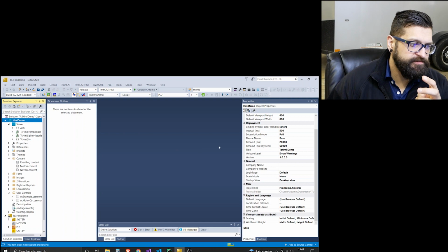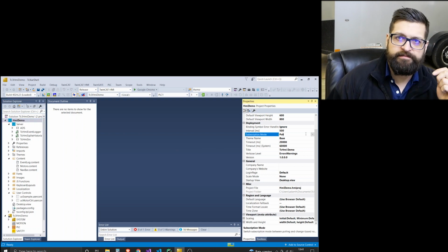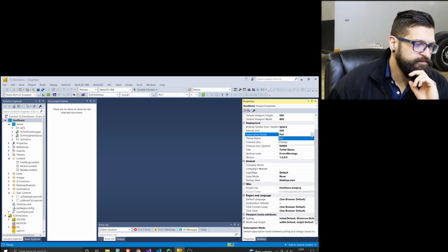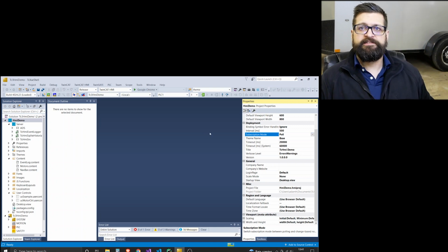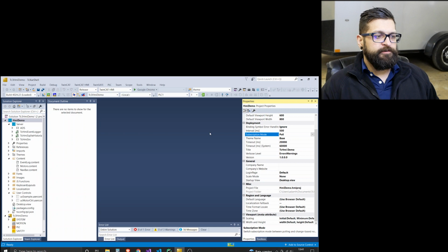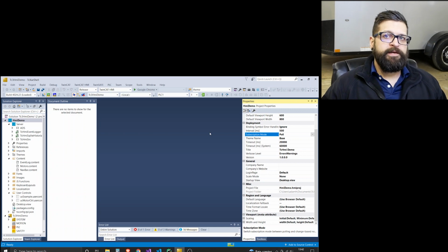You can also do subscription mode on change, so that when values change in the PLC, they're automatically pushed up to the HMI server to refresh the value of that symbol. One thing to note about on change is that if you're dealing with Booleans, that might make a lot of sense because oftentimes those change much slower than analog values.